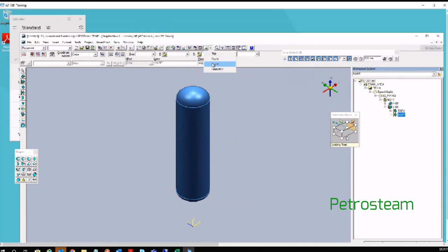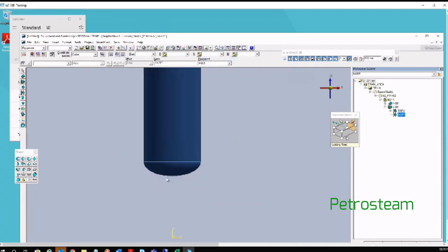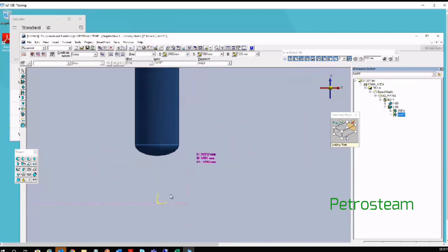Just assume that in the front view a nozzle will come at the bottom like this, and it is projecting out of the skirt. For that I need a through hole in the skirt. To get through holes, which are negative, we have to use some negative shapes to make the holes in the shapes.